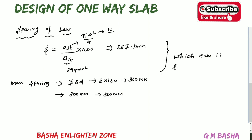The maximum spacing allowed here is 360 mm, but it should not be greater than 360 mm, and you also have to satisfy 300 mm and 267.1 mm.